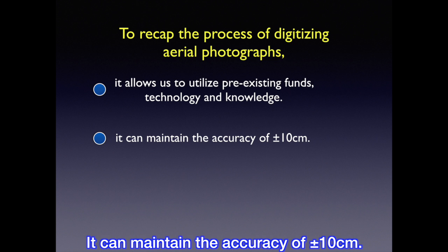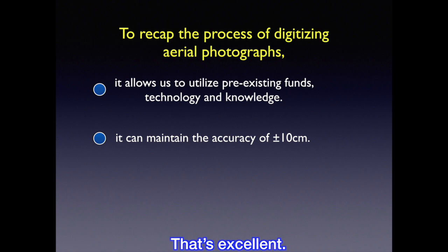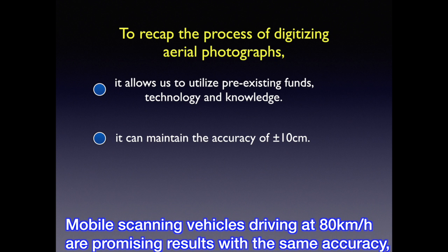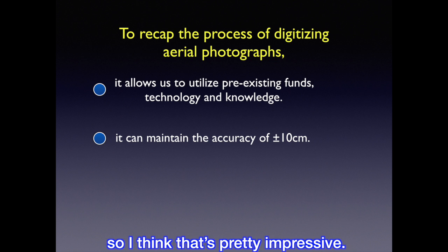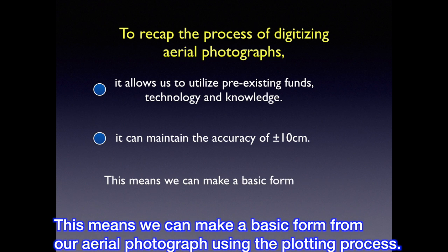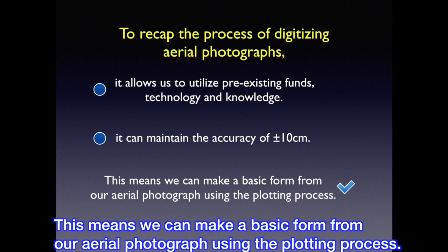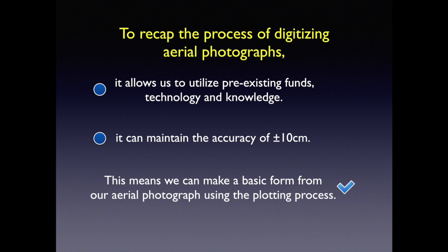It can maintain the accuracy of plus minus 10 cm. That's excellent. Mobile scanning vehicles driving at 80 km per hour have promising results with the same accuracy. So I think that's pretty impressive. This means we can make a basic form from our aerial photograph using the plotting process.